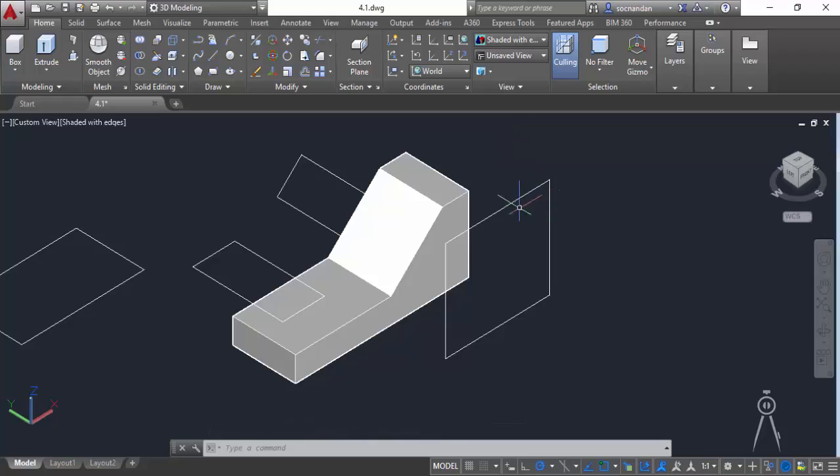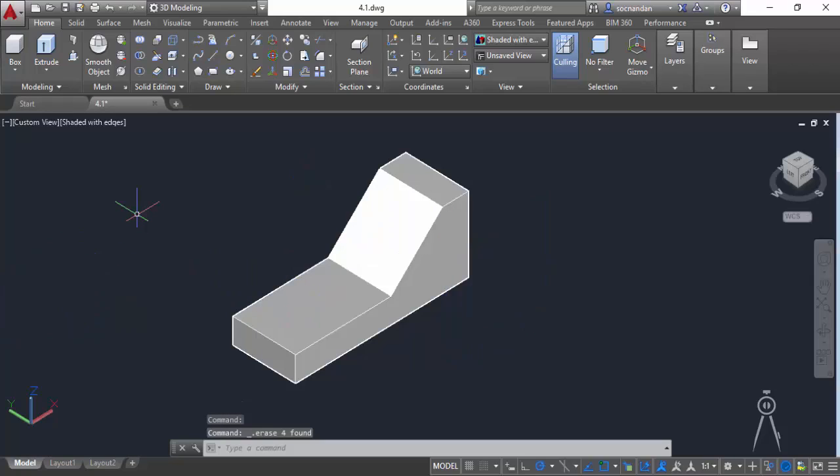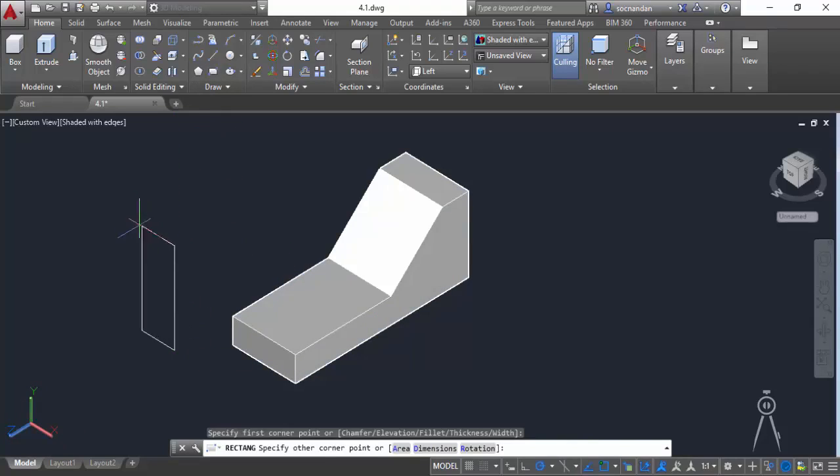Now, what if we are not able to create 3D geometries, or in situations where we have a completely blank drawing area where we don't have any 3D geometry? In those cases, we can use coordinates. So now let's say that we want to make our drawing on YZ plane. Now we can clearly see that YZ plane is also the left plane according to this view cube. So from this drop down, click on this left, and now you'll notice that UCS will change to XY towards left, and now whatever drawing you'll make, it will be made on that plane.